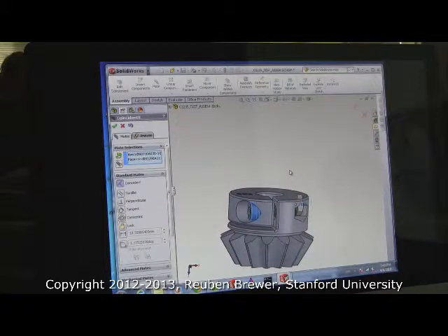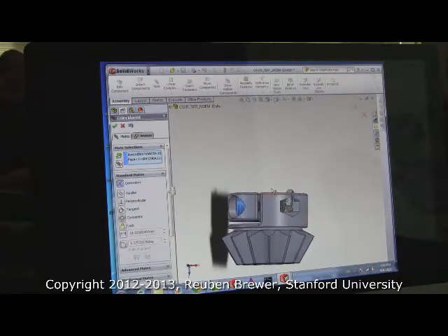And now there's something wrong here. Does this look correct? SolidWorks for some reason does this obnoxious thing where it could either be coincident or concentric. Coincident means the axis is somewhere along that surface. Concentric is what you want. So press concentric and click the green check mark.